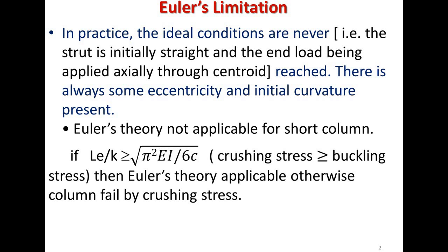The first assumption is that the column should be straight and the load applied is always axial, but in actual practice we can't apply load at the axis. It may be some eccentric, or the column may be slightly bent. That is one limitation. And second, it is not applicable for the short column.